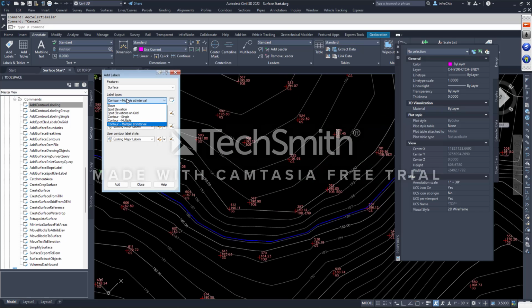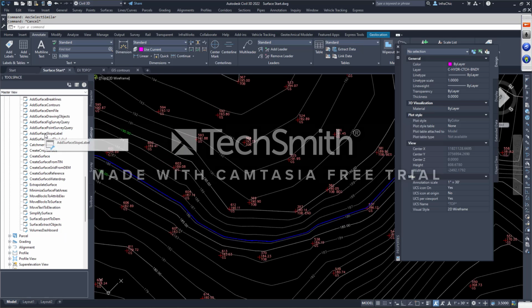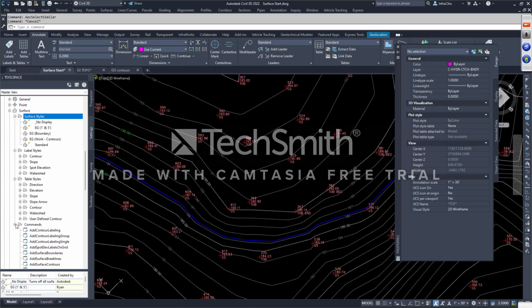All right, so that's pretty much labeling in a nutshell. And again, every time you need to edit something, it's always in the Edit Current Selection dialog to change things, okay? And the commands are right here. How you start a surface, what layer they go on. It's always, what type of layers, what's the defaults that are going to come up when you access the command. That's all controlled on your Settings tab, Surface Collection. Surface styles, again, are shown on your Settings tab, Surface Collection. Same thing with your label styles and table styles.